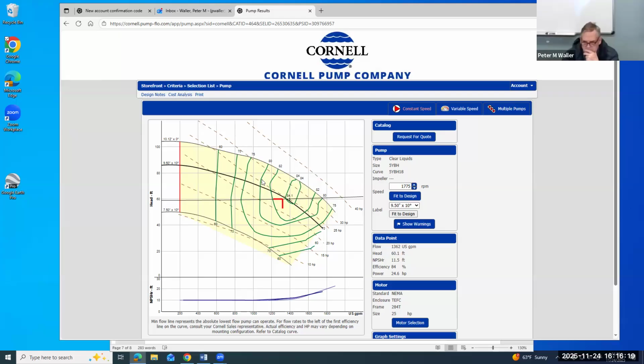And oh, here's the NPSH. Okay, so it's 10. And I've forgotten exactly the meaning of NPSH. I think this means you could be 10 feet above the water level. But you also have to consider things like losses inside the pump and the fittings coming up to the pump. So the book describes it clearly. It's just been a while since I've looked at that. But that's something you have to be very careful of, that your pump isn't pulling water up farther than it can pull it up.